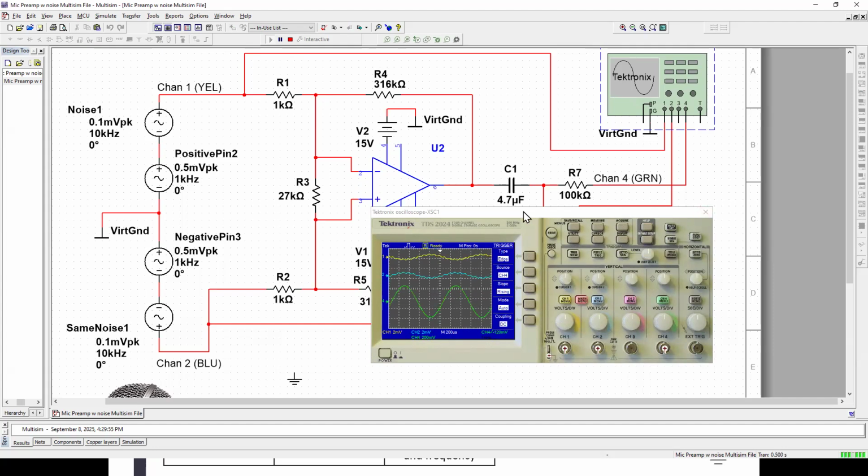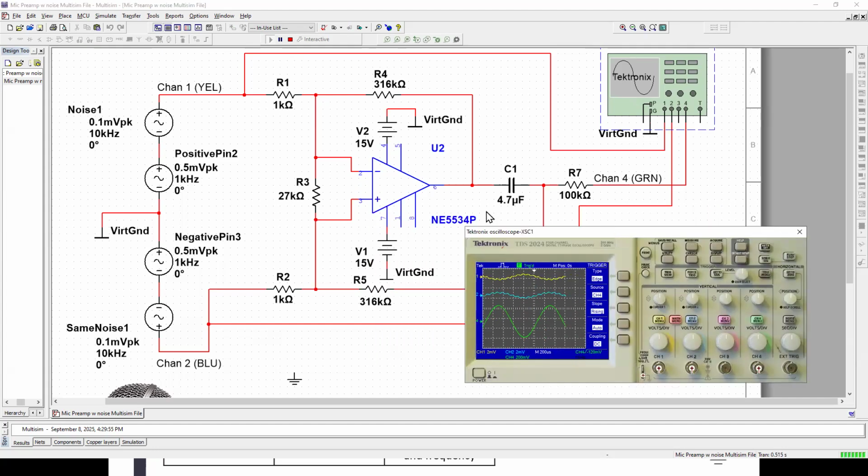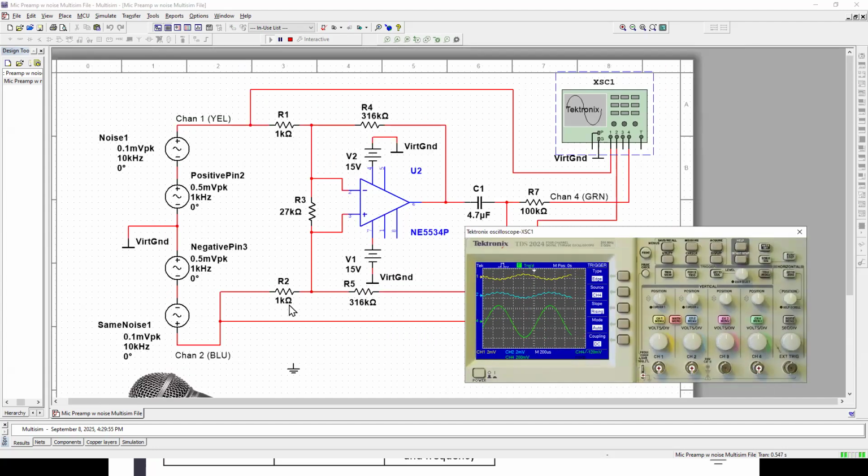That's why in professional audio, for example, balanced lines are used a lot, because over the balanced line, you can send a weak signal over what is considered a long distance, which would be 200 feet, 300 feet.